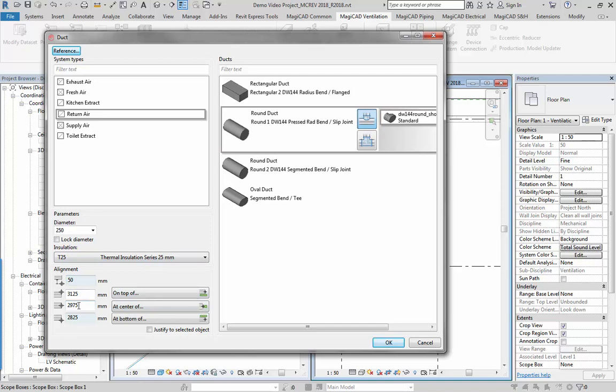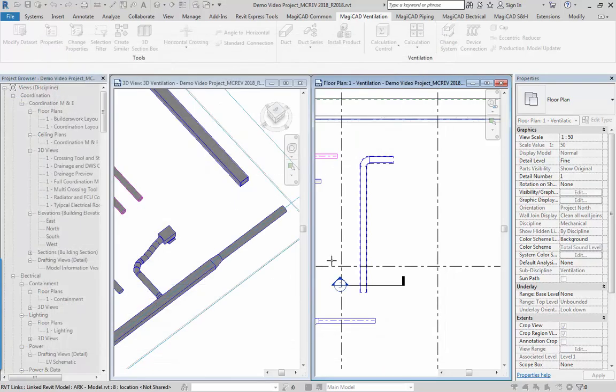And then with this you can also set as normal. You can just put your normal offset in like in Revit, but you can also choose the bottom of the duct, and you'll see the other figures update in relation to the diameter, like so. And there are some tools down here as well where you can say I want to justify or run my ductwork on top. So if I click justify, I can justify this circular duct, top to top of this rectangular duct.